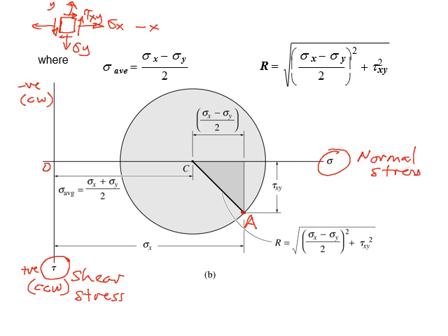If you look at the Mohr circle closely, you will find several things. Number one, the average normal stress gives you point C. Point C is based on the average normal stress value. This is 0 on the left, so the average normal stress will give you point C. The other thing is the radius of the circle is given by R, which is equal to tau max.